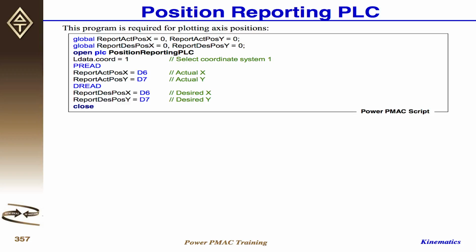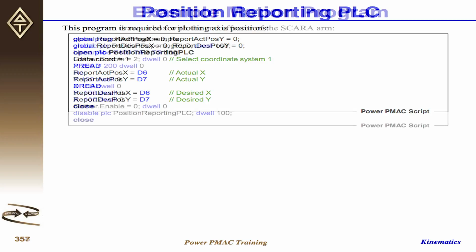Okay. The other thing for this is that within a motion program, all the variables inside are local, so you cannot extract them out. If you don't use this, you cannot actually get it out, because they are all local variables, so the global status, you cannot see it. Okay? That's the reason why we want to use this, to extract that out to a global variable, so that you can plot this.